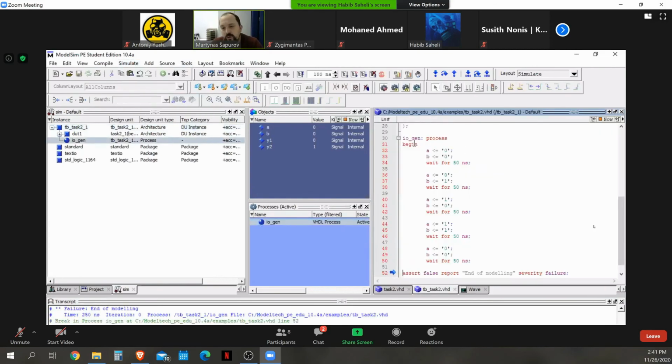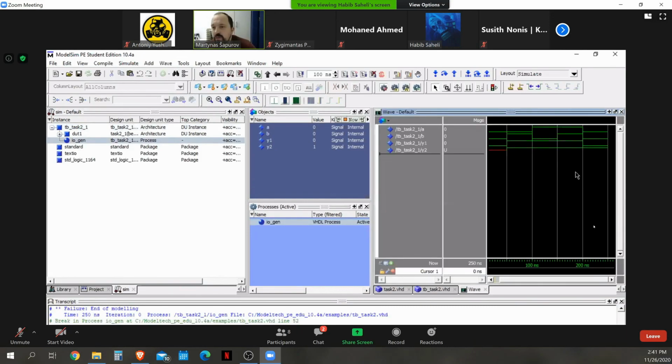All right, very well. And now you see that the first one works properly, and it's just a serial circuit of two-gate OR elements. The second one, as you connect the output of our OR element directly to the input, gets stuck in the value of 1 and does not react to anything. And prior to that, the value is still unknown. So it's completely inappropriate operation.